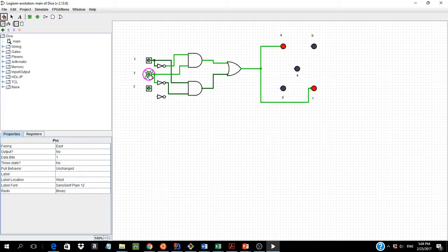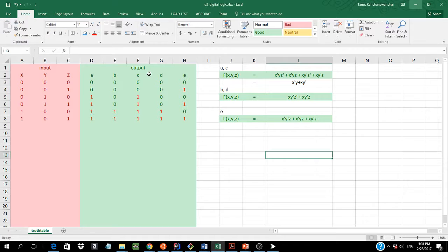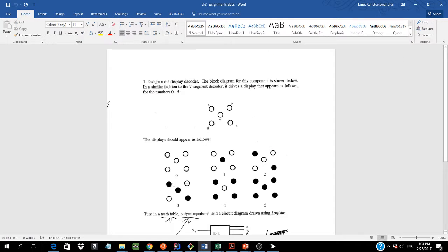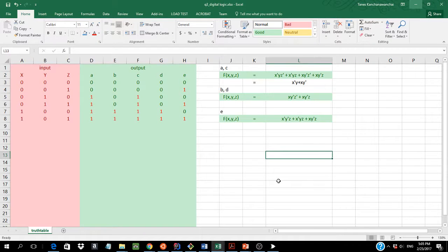When it's 010, it's going to give 2, right? Let's verify. There you go. So we designed exactly 2. That means you simplified it correctly, just 10, right? If you don't simplify correctly, then you see why we need to simplify. You reduce the work. You don't need 3 ORs and tons of AND and NOT. See that? And that's how you create a circuit. So let's finish that up.